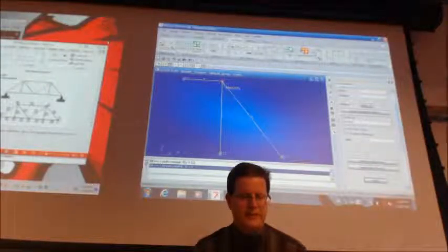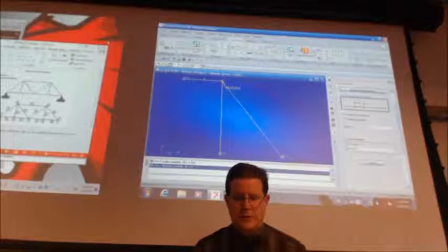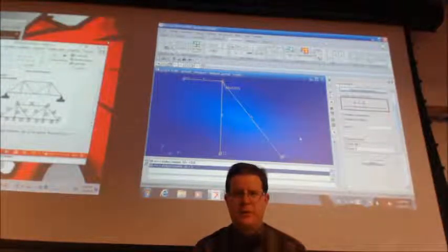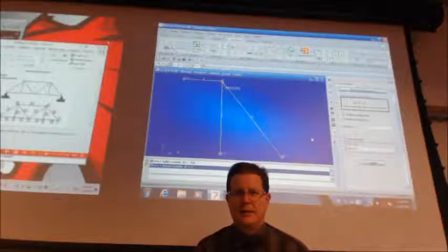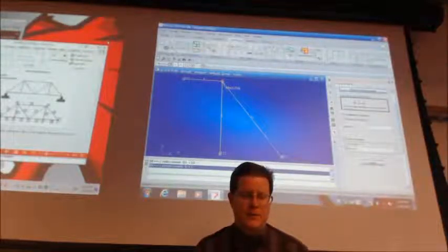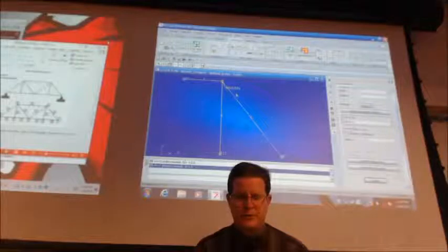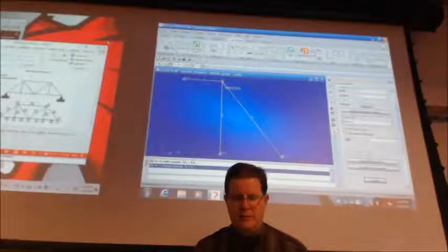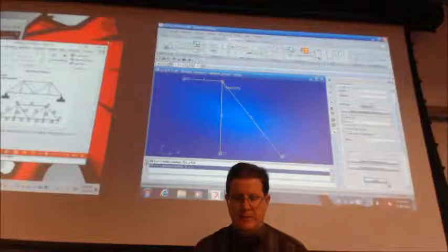Oh, okay, uniform. Uniform, you just set number of elements, make sure it's set to 1, and then you just pick each curve and hit apply. Yep. And then I went to measures and picked each one of the curves and set apply.